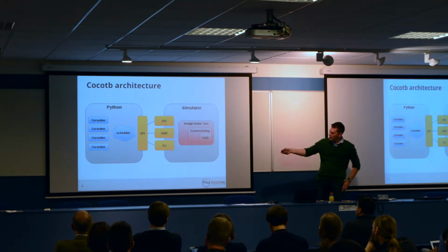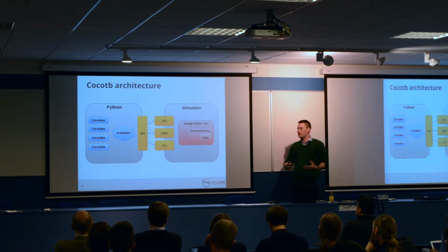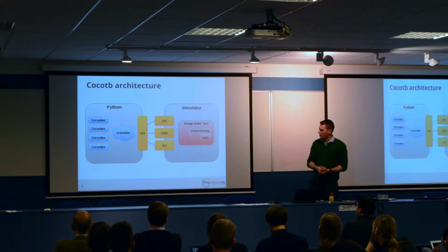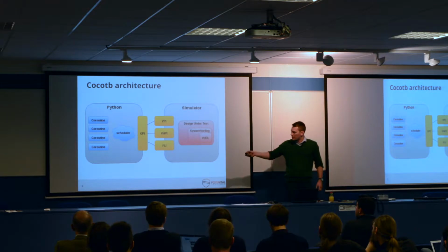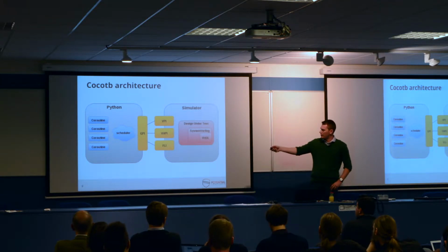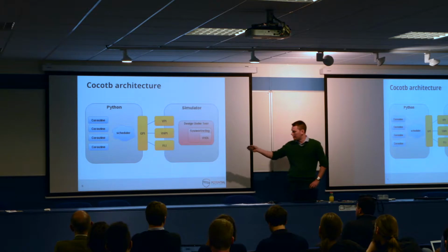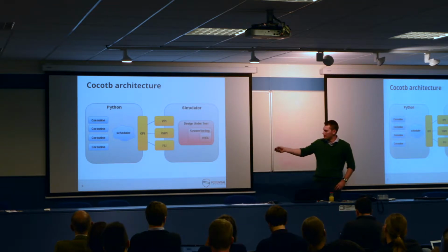On the Python side, we use coroutines for concurrency, so you can have massively parallel, many flows of execution running in Python. So your test is made up of lots of coroutines running in Python that are accessing the design through this C++ layer in the middle.